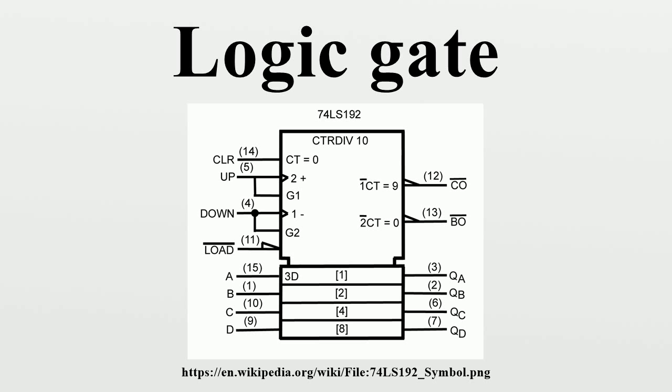described with Boolean logic. Logic circuits include such devices as multiplexers, registers, arithmetic logic units, and computer memory, all the way up through complete microprocessors, which may contain more than 100 million gates. In modern practice, most gates are made from field effect transistors, particularly MOSFETs. Compound logic gates such as AND-OR-INVERT are often employed in circuit design because their construction using MOSFETs is simpler and more efficient than the sum of the individual gates. In reversible logic, Toffoli gates are used.